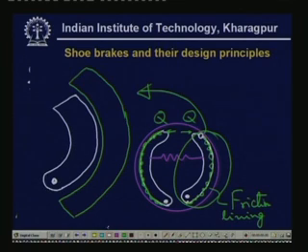This is the fulcrum, and there may be a lining. So, when this rotates, of course it goes to some position. Here we see that there will be more deformation here than here, because now it is rotated about this point. So, somewhat like this. The deformation is more over here, and therefore the pressure will be more on this face.